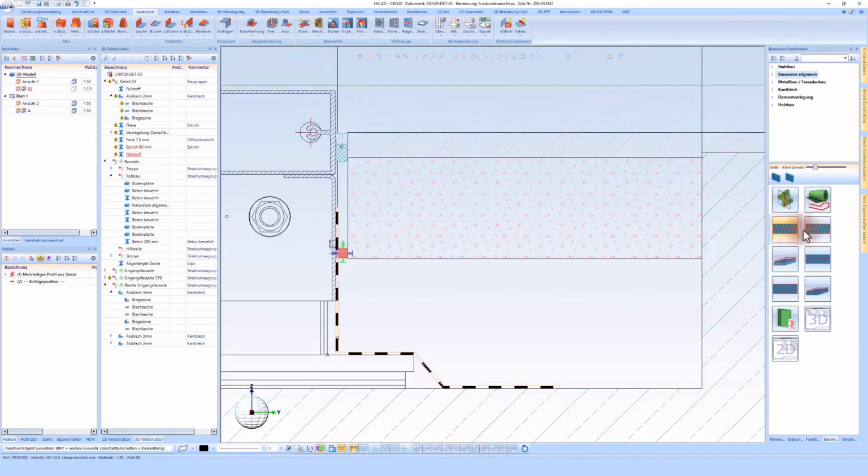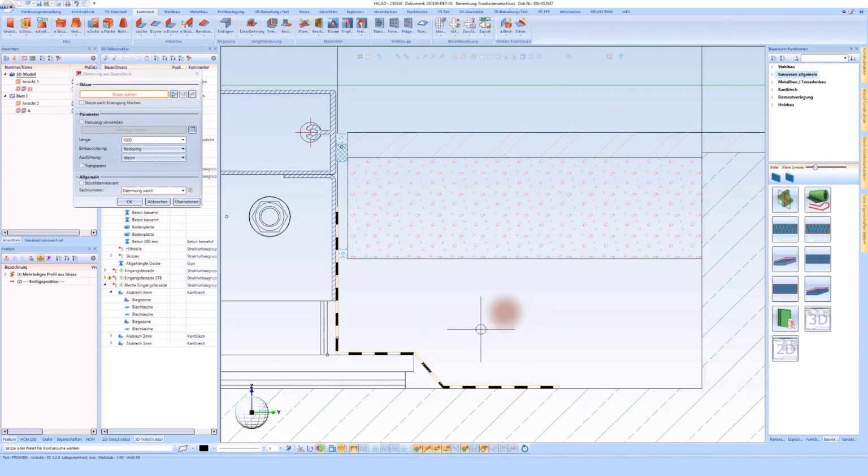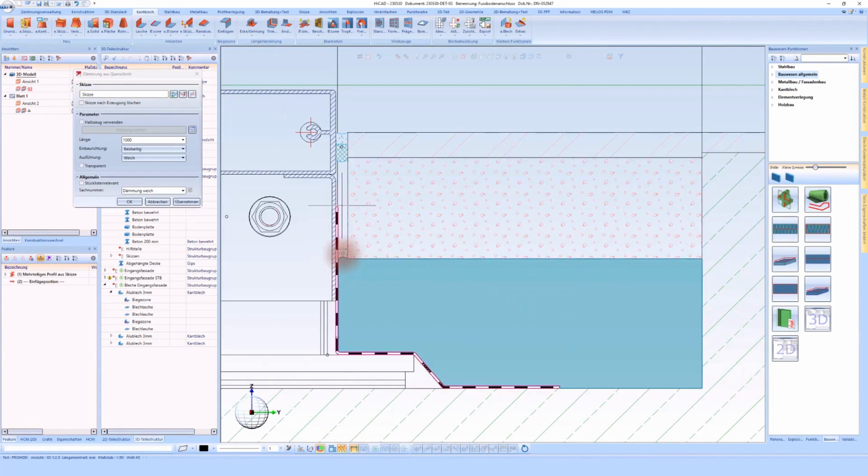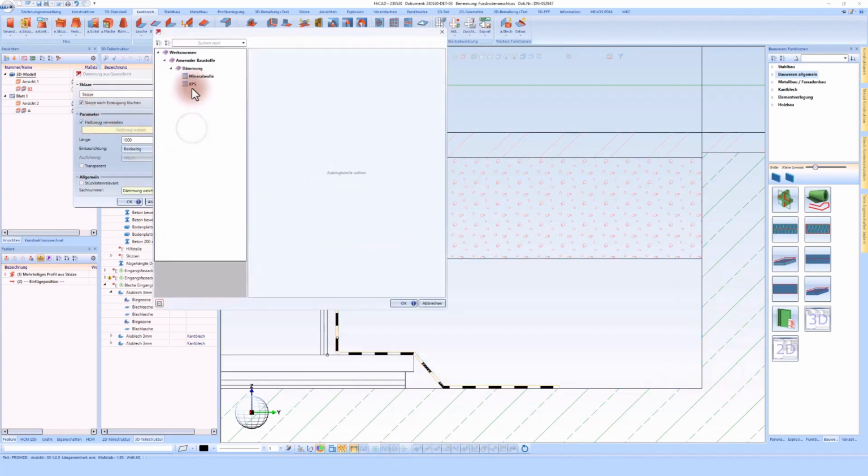I can work with the insulation here, then with the middle mouse button, I can cancel this area and look for a point here. Since this area has now been closed, because I do not want to carry the insulation into this area, I will create my insulation here. This means I can choose again from a half cut.